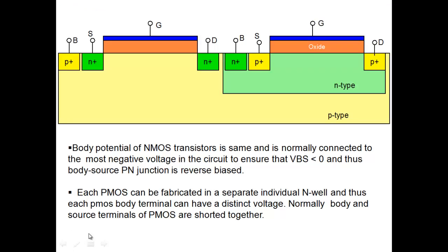All right, so this shows an N type and a P type MOSFET side by side. See, the substrate is P type, so NMOS is made right here. N plus, P plus, this is NMOS here. And PMOS is in a separate well like this here.